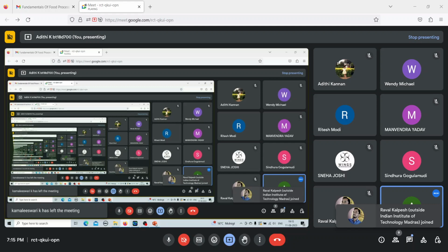So now since delta T is not constant throughout, we will keep multiplying delta T and then summing it up. Previously, we took out delta T outside the summation. We added only the L values and then we multiplied by delta T. Now here, since the delta T is not the same value throughout, we will multiply L into delta T first and then add. So in the first case, the delta T is 25 minutes. In this case also delta T is 25 minutes. In this case delta T is 20 minutes.